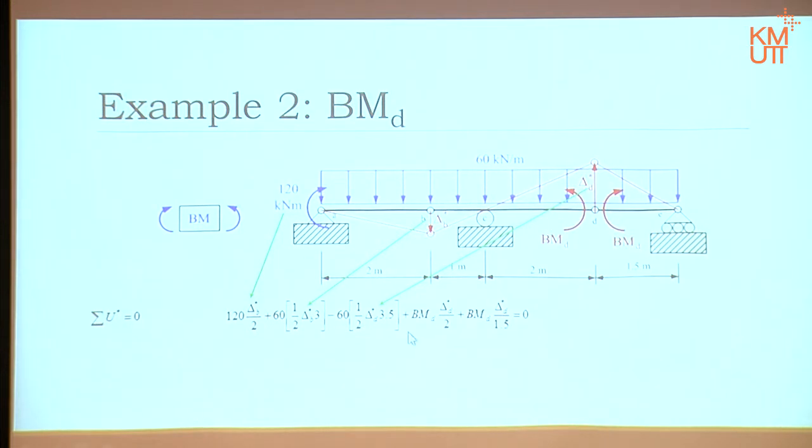That is the 90 degree height, this time delta D, and times the base from here to here, 3.5 meters. And that bending moment rotates by this angle, which is delta D divided by 2. That bending moment rotation, that angle, delta D divided by 1.5. Okay, that's it. That's all.